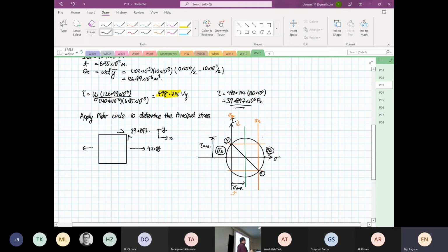And before we do anything, let's do the real engineering work, right? Let's do 3D Mohr's circle. We know at that one stress state, Z will be over here because Z has 0 normal stress and 0 what? Shearing stress. So therefore, it is safe because if I were to draw 2 other circles, one circle is here, right? And the other circle is over here, right? We know the XY plane will carry the highest what? Maximum shear stress. Always check.